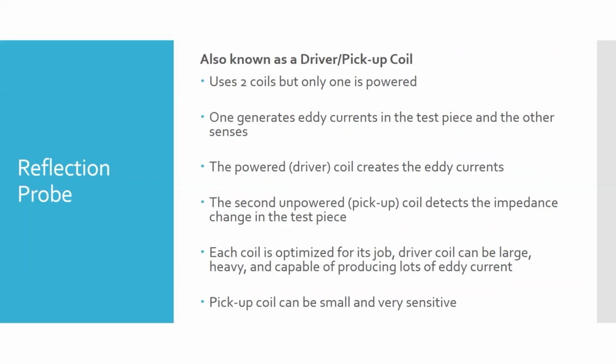especially in materials like aluminum and titanium that are not ferromagnetic. They don't really want to create a magnetic field very well. So then we have a pickup coil that's much smaller and more sensitive to those relatively small, relatively weak fields that are generated by the eddy currents. And that way the power being sent in to drive the coil will not overwhelm the ultimate signal coming back through the pickup coil.